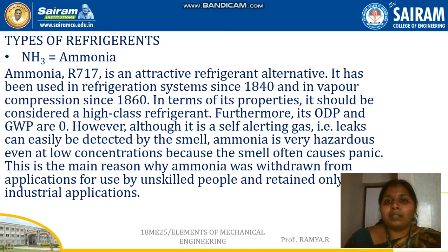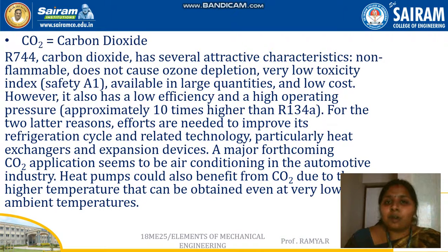The next refrigerant is carbon dioxide, indicated as R744. Carbon dioxide has several attractive characteristics: it is non-flammable, it does not cause ozone depletion, has very low toxicity, and is available in large quantity and at low cost. So it satisfies all the properties of a refrigerant. However, it also has low efficiency and high operating pressure. For the latter two reasons, efforts are needed to improve its refrigeration cycle and related technologies.